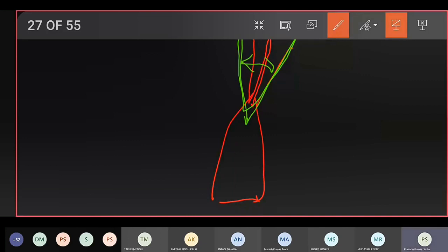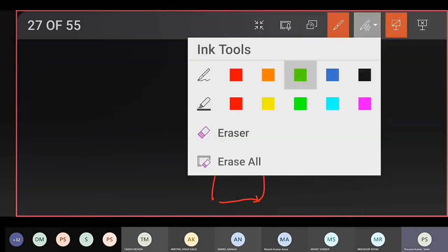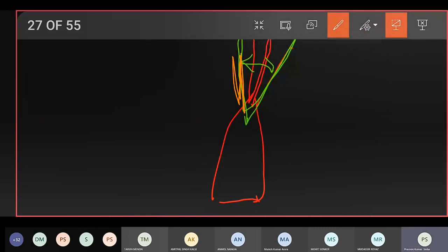In between, rudder will not be applied, because when she is coming to this port side deviation, the waves will take it to this side again, then again to this side. So allow it to happen. So yaw control should be narrow in good weather and wider in bad weather. We can allow 2, 4, 5 degrees in bad weather, and keep 1 or 2 degrees in good weather.